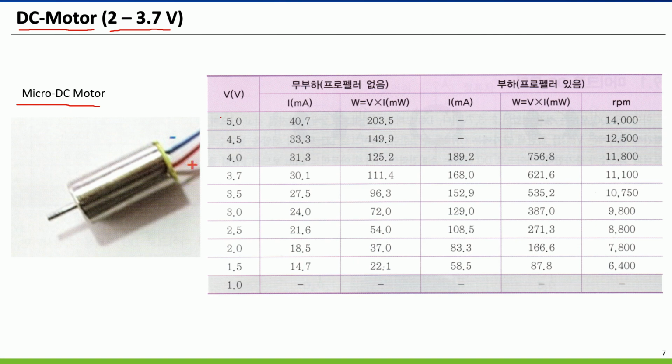But you can also give it 5 volts, but be careful about this one. Maybe there can be more heat generation that can damage your motor, or maybe more than 5 volts. You have to be aware of this motor.